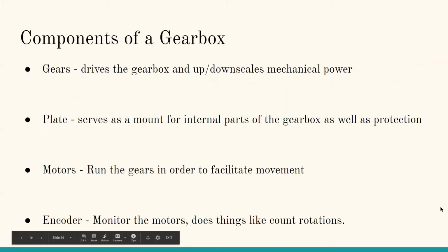All right, so we're going to start with the components of a gearbox. So how do they work? Well, gears. In the name gearbox, it's probably fairly obvious that they're there. They drive the gearbox, and they take in mechanical power, and they can upscale or downscale. For example, if you had a large gear driving a small gear, one rotation of the larger gear will be more rotations of the smaller gear, so it'll turn faster.